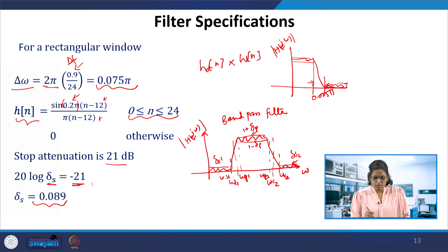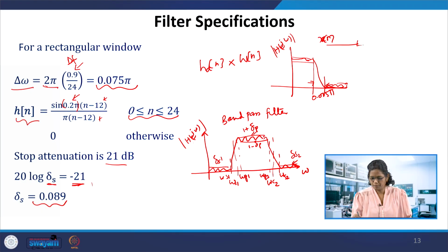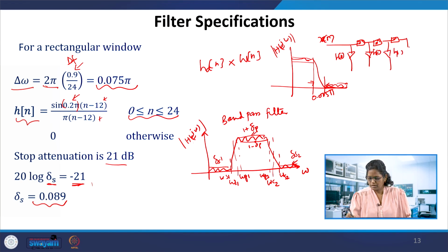But using these filter coefficients, we will be making a Verilog module, with the expression for y of n in the case of an FIR filter. Suppose we have h of 0, h of 1, h of 2, and for example up to h of 3, in the linear phase configuration.